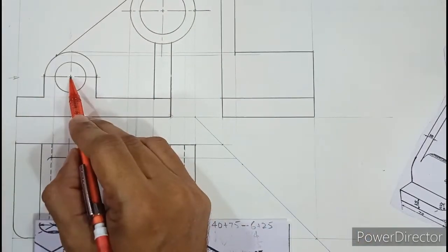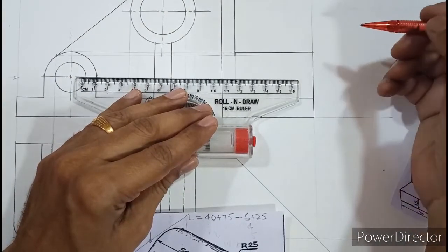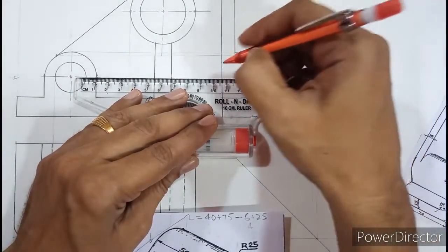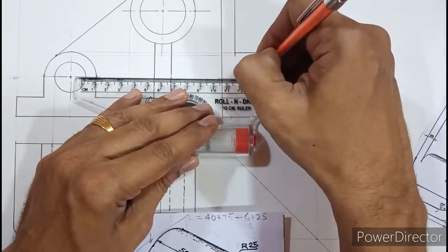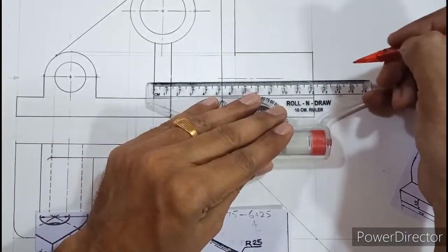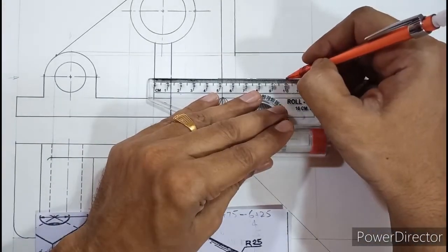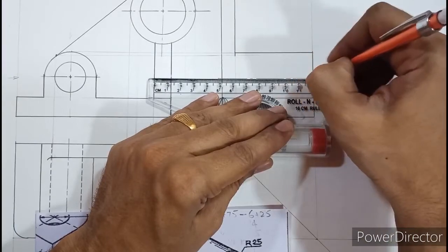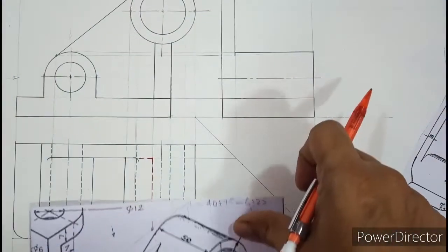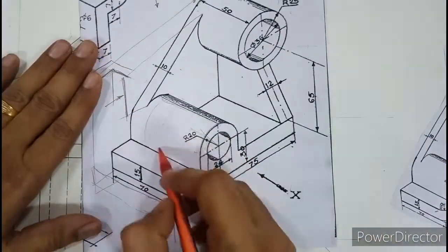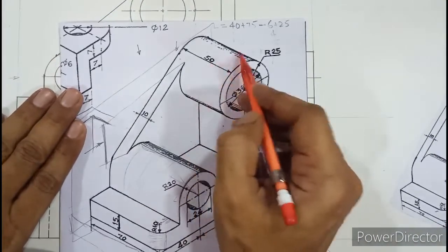Or even if you look here, look at this plus sign that you marked. So in connection to that, we need to show an axis line over here, a combination of big dash and small dash. So it's a curved surface. So we need to show a medium dark axis line. Okay. So once this curved surface is ready, you can see one more curved surface on the top.